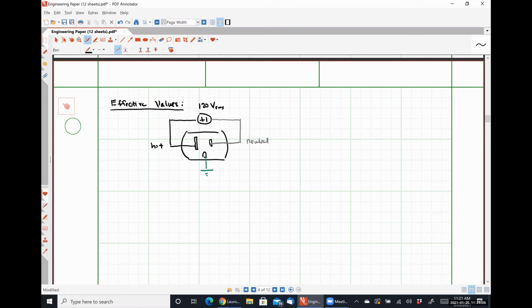So as a time domain function, this voltage would technically be represented as v(t) = 169.706 cos(120πt + θv), where θv is some phase angle that depends on when we start measuring our circuit. This would be in units of volts.